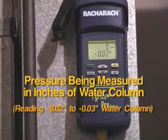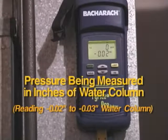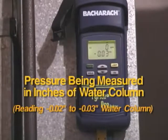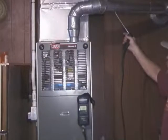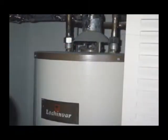The vent gas temperatures in these mid-efficiency furnaces are designed to be in the same range as the older draft hood equipped models after dilution. It's possible for the pressure in a vent system connected to a fan-assisted appliance to be negative because once the draft has been established, the draft action should be stronger than the fan pressure rise if the vent is designed correctly. One interesting phenomenon that can occur with fan-assisted Category 1 appliances stems from the fact that they can be